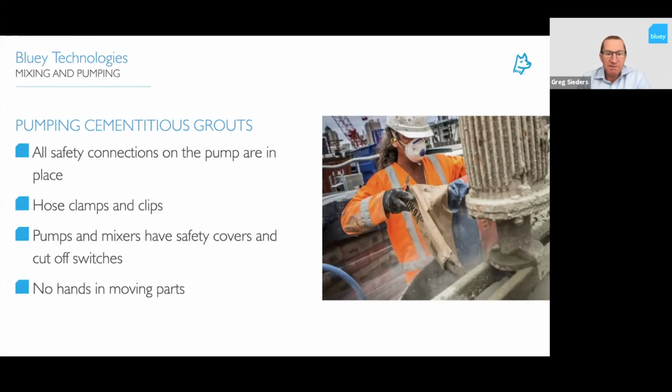Make sure all your safety connections on the pump are in place, so hose clamps and clips, so you don't have any blowouts. If you're using very high pressures, having chains on there is an extra safety measure.